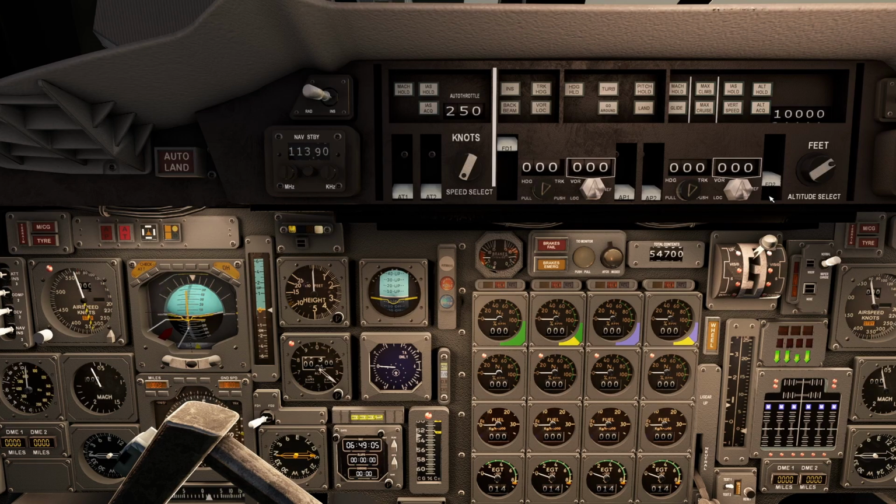We're going to turn on flight directors. Later on, if we engage auto thrust, we're going to click indicated airspeed acquire to reach 250 knots. We're going to click INS, so the airplane is going to follow our very simple flight plan, and altitude acquire to reach 10,000 feet.